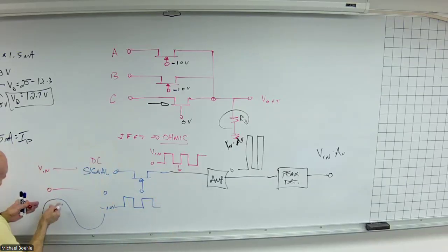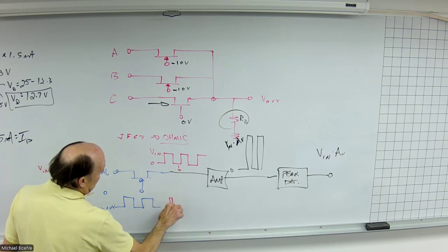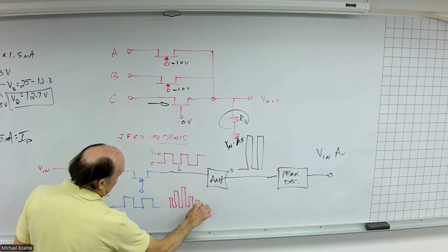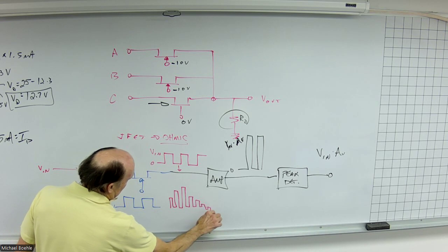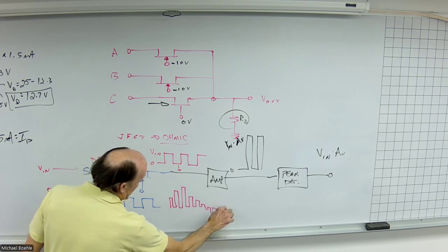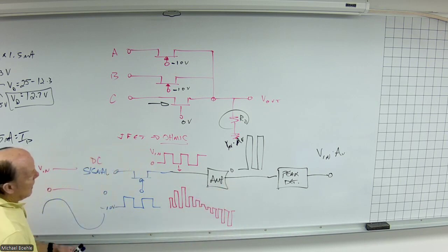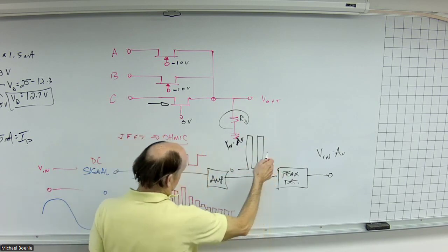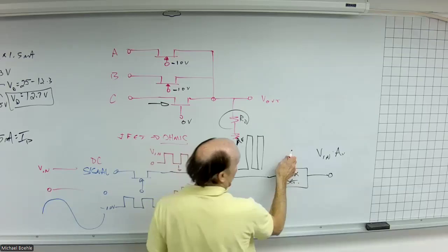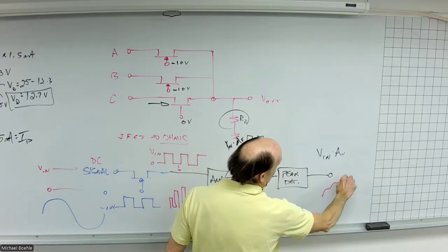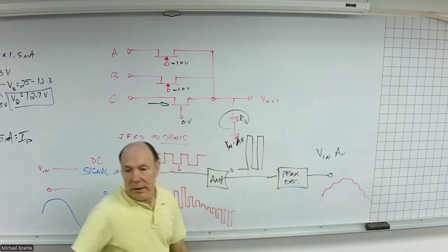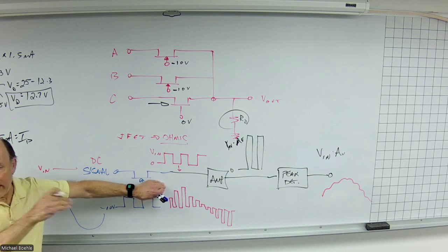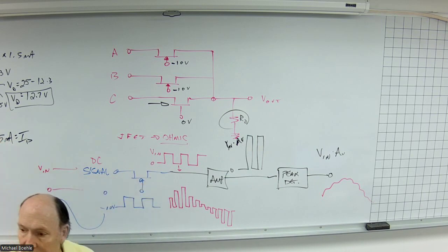So now, instead of having a sine wave, I end up with this, etc. Okay. Well, I'll still amplify this into that. And now, as I make this bigger, it has the same shape. My peak detector will basically give me back that amplified sine wave. So by chopping this up at a higher frequency, I can use my standard amplifiers to go ahead and amplify.